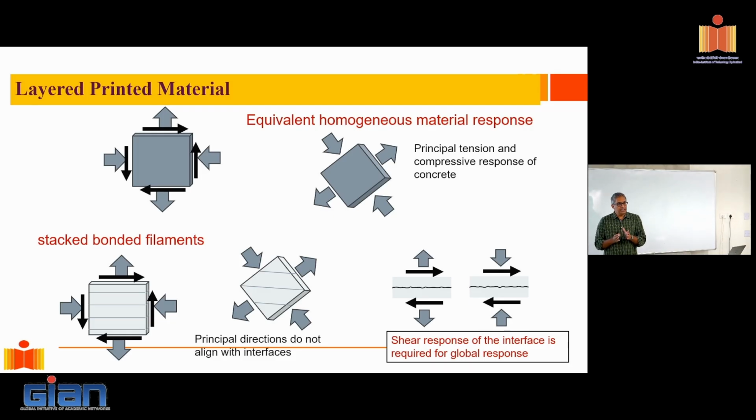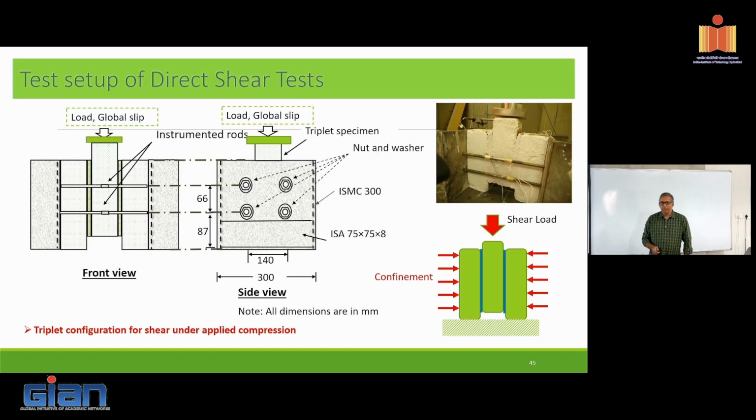Either it's pure shear, shear plus tension, or compression plus shear. This has to be understood. And as correctly pointed out, we have to go to masonry. So we have elements, materials that we've been using for centuries, which have these natural joints. Same problem happens there. Suppose I have a masonry. Right? Now, masonry has vertical and horizontal joints, and if you try to transform your stress field, what happens? The material doesn't rotate, so you end up with exactly the same problem as what you encounter in masonry.